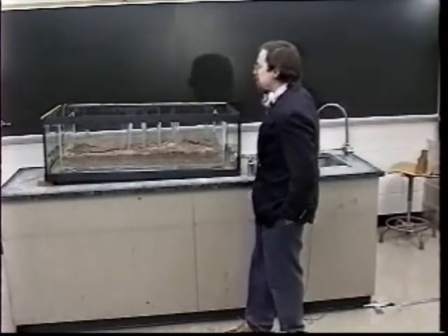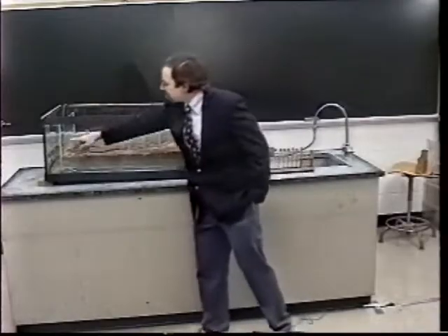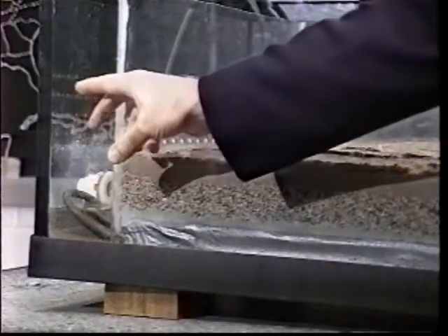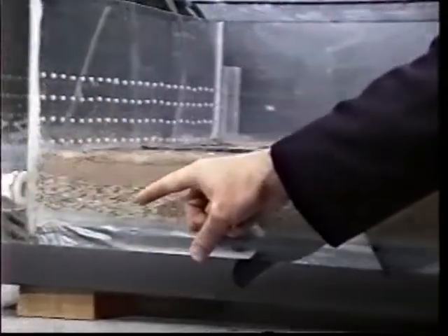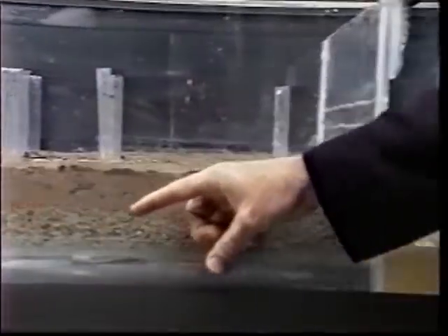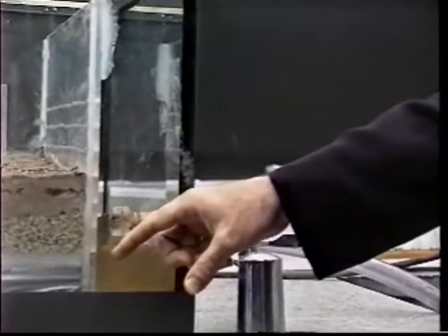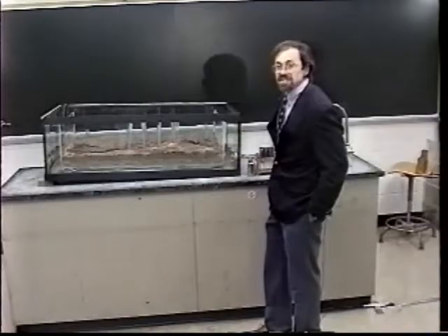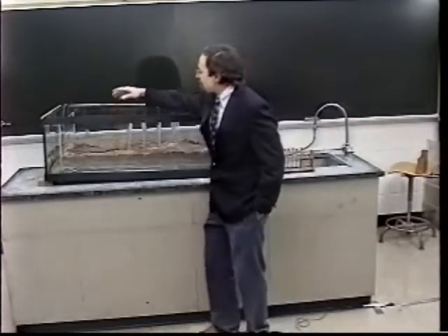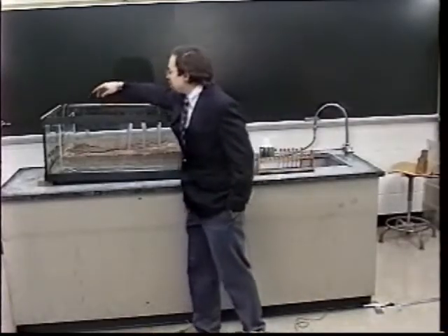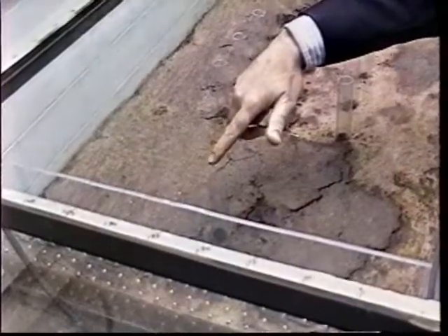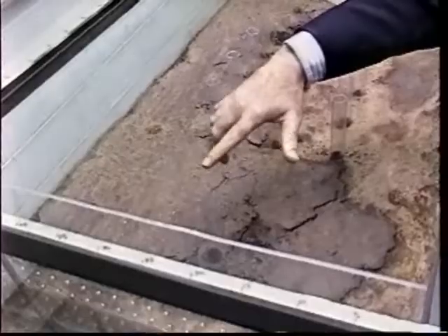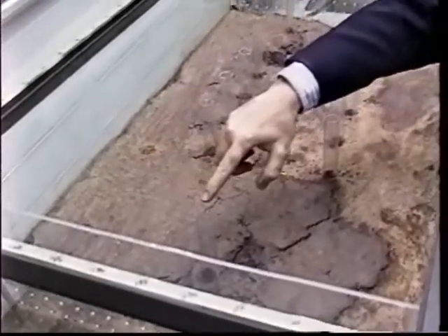What we do is we bring in some water from a tap and fill a tank on this side of the apparatus. The water then flows through the aquifer layer, coming all the way to this side and then exhausting out of this tank on the side through a pipe into the sink. What we have on top is a series of wells. The well on this side, closest to the input side, is an injection well. This is where we're going to dump our dye to track it.